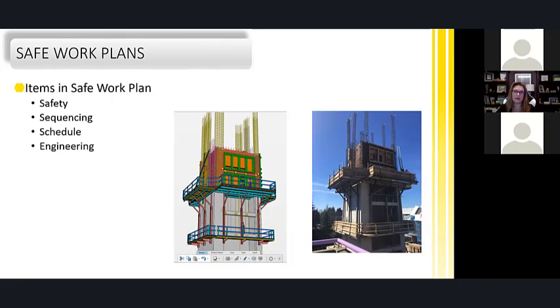In the planning, we also talk about safe work zones and any no-crossing zones. What are the slings looking like? What are the taglines looking like? How many radios are required to actually perform this installation? And then we would also highlight any major lifts that would have to be specifically engineered by a local company here. Sometimes our generator is a little iffy, and we like to go the extra mile and make sure that we have that as an engineered lift, just so everybody feels comfortable.